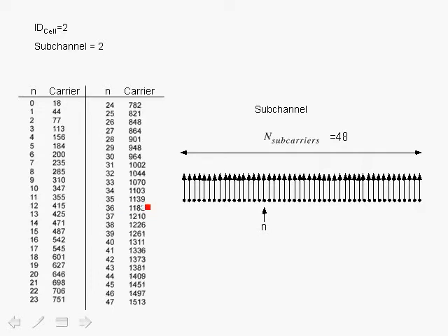None of the carriers are adjacent to each other, and we have within a subchannel carriers ranging from lower index carriers all the way to higher index carriers, and a permutation thereof. So we have achieved our goal in terms of permuting the carriers in order to have a more robust communication link with multipath fading channels with deep fades.